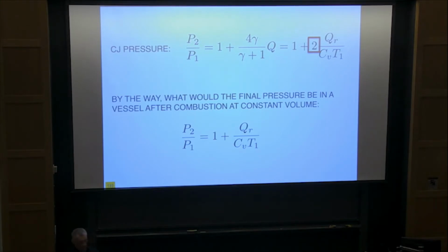And since you are in a constant volume bomb and rho cannot change, pressure is also in the same ratio. So you see, theory tells you that if you have a detonation somewhere, the maximum pressure you can reach is this number, generally small compared to that one, so that it's 2 times what you have in the box normally.